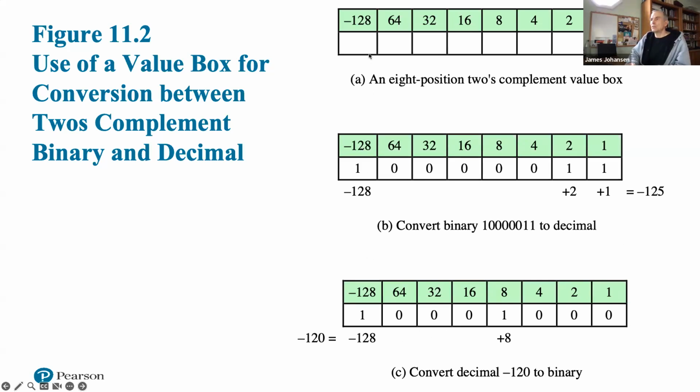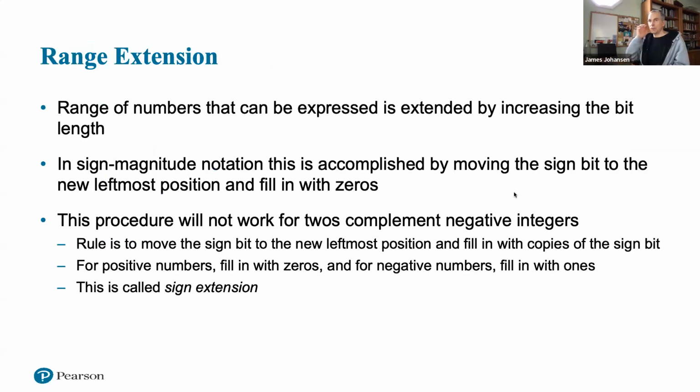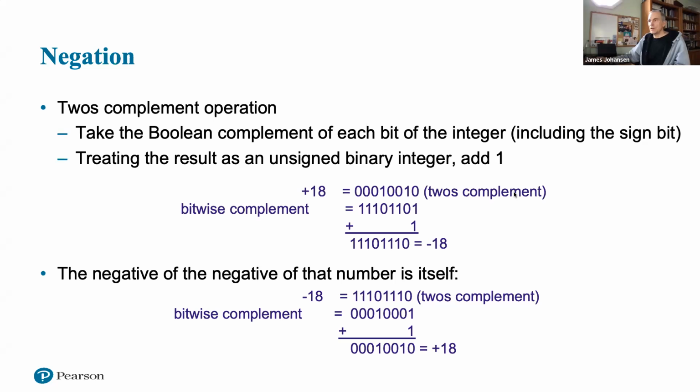So this is just a little bit of a perspective for an 8-bit number, having the most significant bit carry some meaning. Well, we talked about a lot of this, and so how do we take the negation? We do a bitwise complement. Wherever there's a one, there's a zero. Whenever there's a zero, there's a one, and you add one.